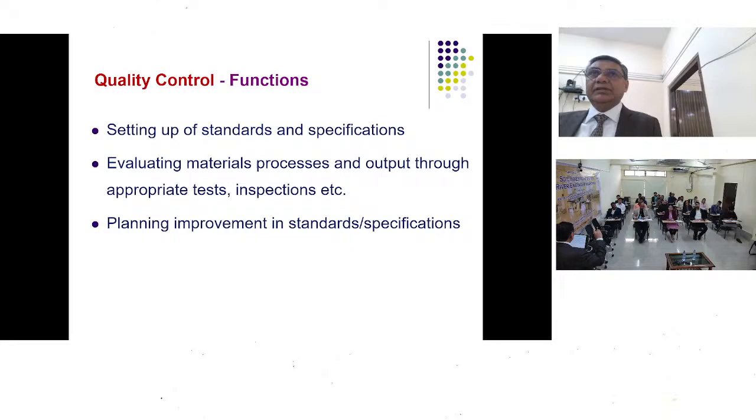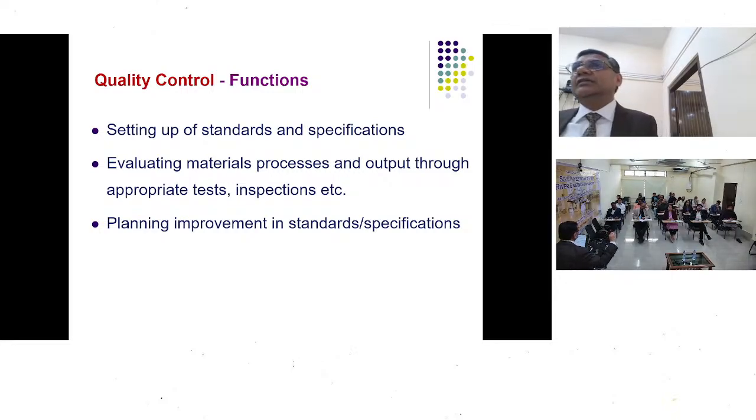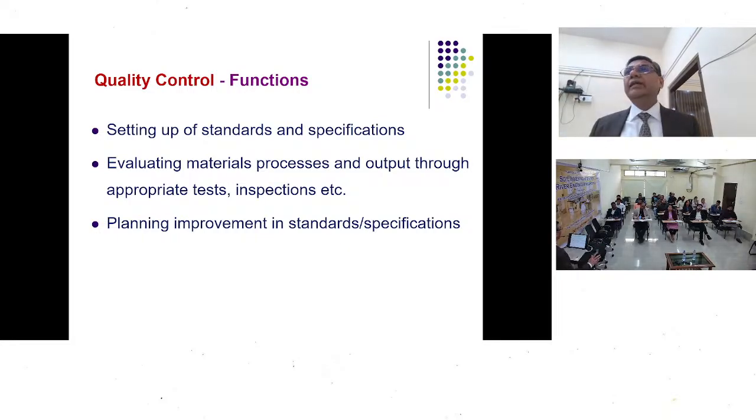Suppose the contracting agency is providing a greater depth, suppose they put a 40 centimeter depth, and you are going to get a lower density, then again a higher density, again varying to low. So we are having thin zones of weaker material there, which is not compacted to the desired density. So ultimately they are planes of weaknesses. And when these planes of weaknesses are subjected to water load, they may lead to erosion of the material.